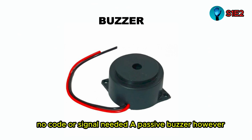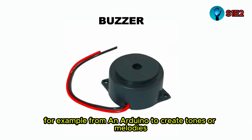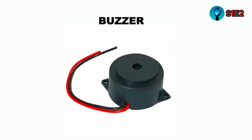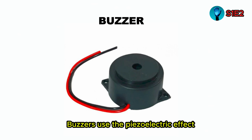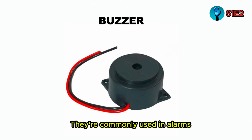A passive buzzer, however, requires an external signal, for example from an Arduino, to create tones or melodies. Buzzers use the piezoelectric effect, where a special material vibrates when voltage is applied, generating sound waves. They're commonly used in alarms, timers, and robotic alert systems.